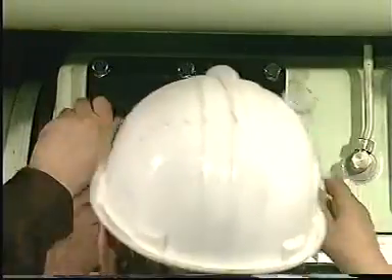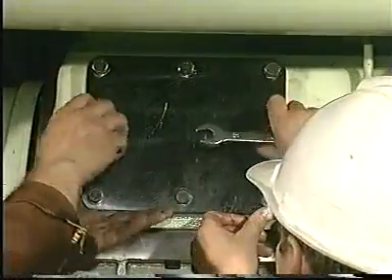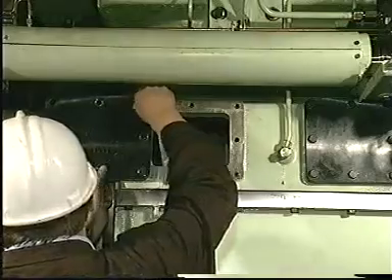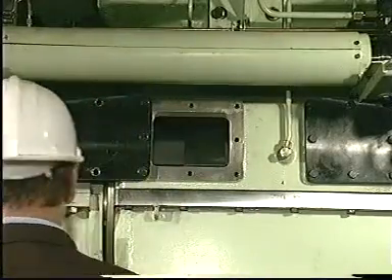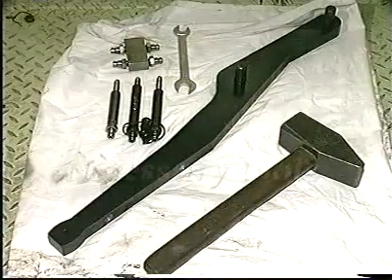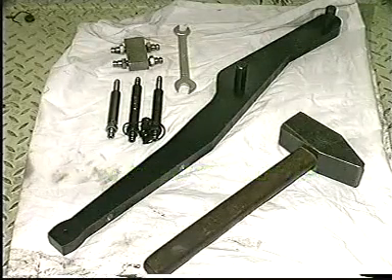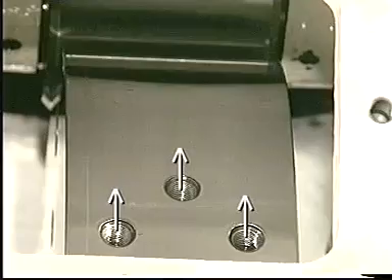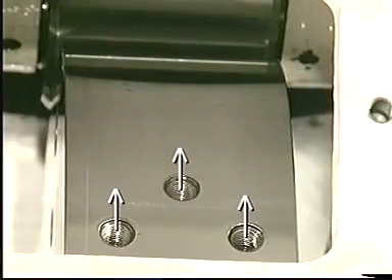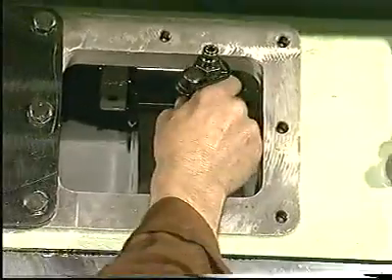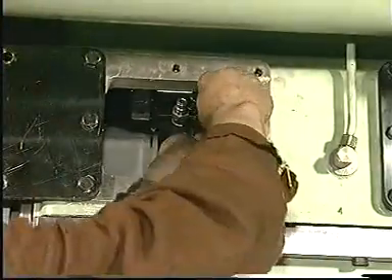Carry out fine adjustments through the small cover. If the camshaft has been dismantled or if new cams have been mounted, adjust the cams before mounting the lower part of the camshaft housing. Remove the plugs from the cam, and insert copper gaskets. Mount, but do not tighten the snap-on couplings.